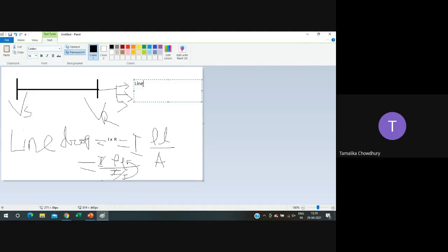So line drop is equal to IR for a single phase, right? This one, IR for one conductor. If it is three conductors, it will be 3 IR. Is it visible to all? Yes, ma'am. So I'm slightly adjusting so that it becomes bigger to see.